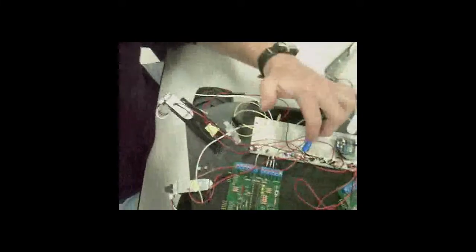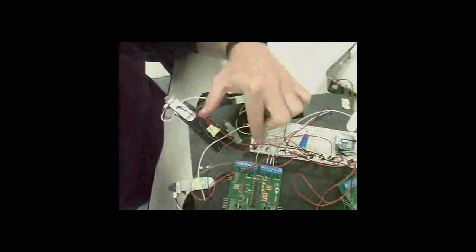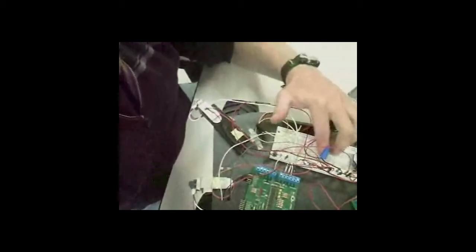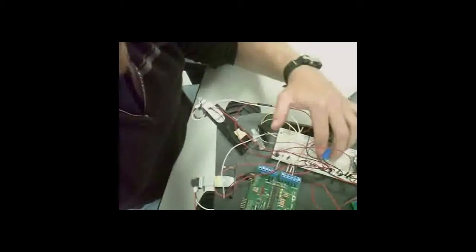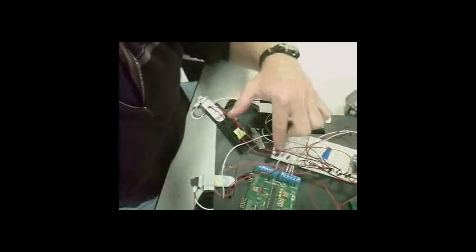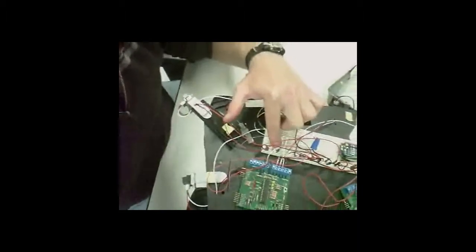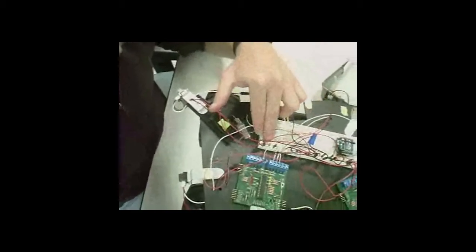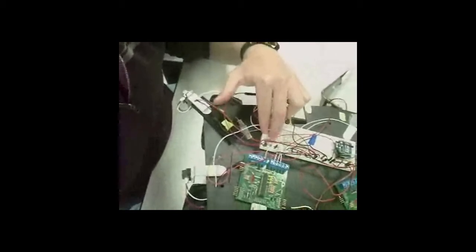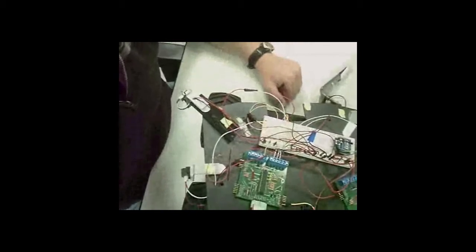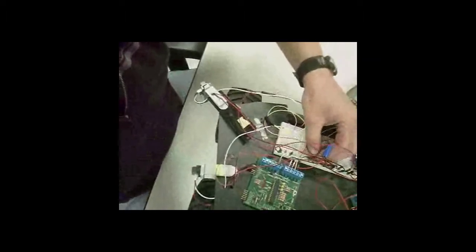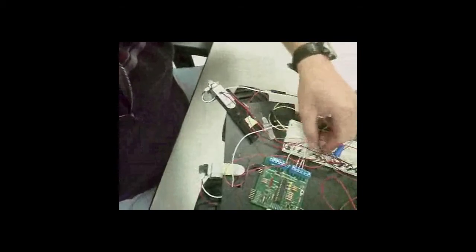On our breadboard, we have several capacitors. Each of these capacitors serves a purpose. The 4 smallest capacitors are 10 microfarads, and they're used for when the IR sensors collect data. Anthony will talk about this more later. The larger capacitors are decoupling capacitors, and they are for when there are different types of power surges on the board in order to avoid any problems. To demonstrate other aspects of our design, I will remove all of these wires from our breadboard.